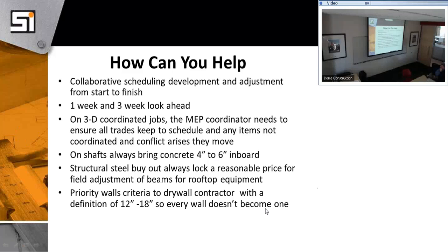And priority walls, to define that ahead of time. It's not 36 inches, and every wall's a priority wall. The guy builds all his walls, and I guess us mechanical, everything's a priority wall, so defining that ahead of time would help us. Everyone wants to go in first. Whoever's first has the lowest labor costs. And so that's a priority wall. So if you define it ahead of time, and we put it in your contract, or put it in part of the bid documents.